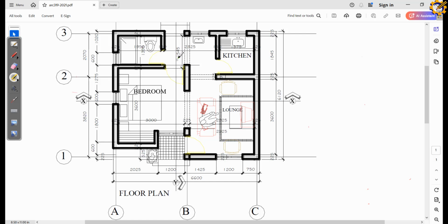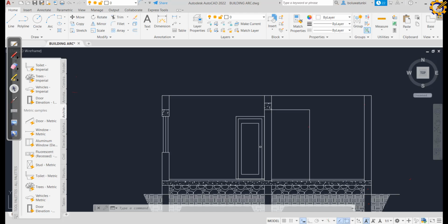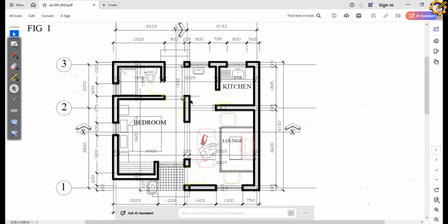Now, if this area is a door, the door is closed, I can't see anything beyond the door, but this area is a beam, which is an opening. Definitely I'll be seeing this particular window, so I need to show that window also. And what's the distance of that window over there? Let us confirm that the window is 900, from this wall to my right hand side, window of 900, and height of 1200.